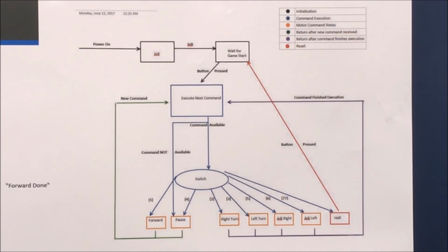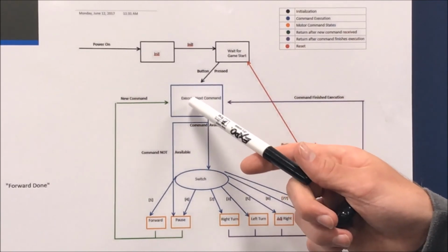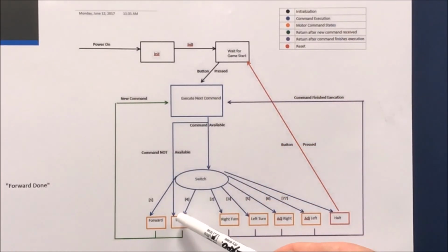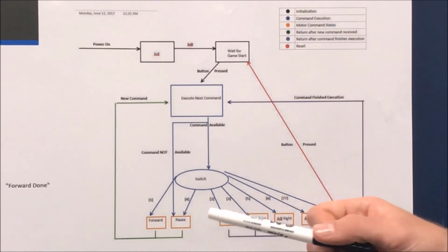For the captor rover, it also becomes activated when the button on the trapped rover is pressed. The main difference is that rather than the sensor thread feeding the commands to the motor, the commands are coming from buttons on the server. So once it becomes active, it will not have a command available and will go into the pause state until the user presses a button indicating which direction it wants the rover to drive in.